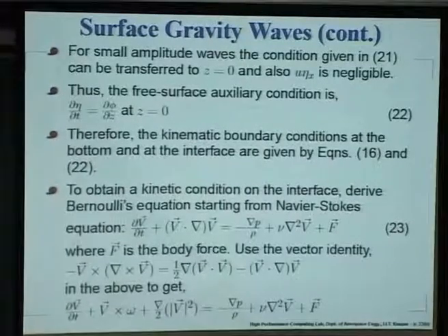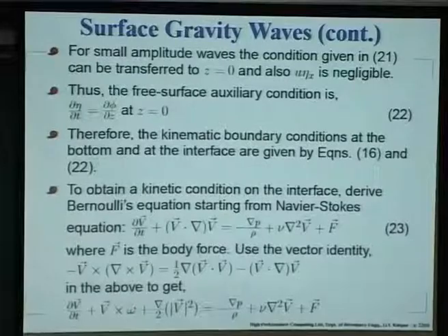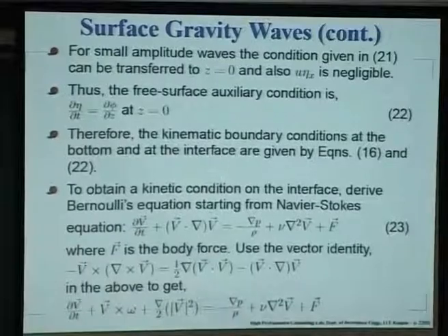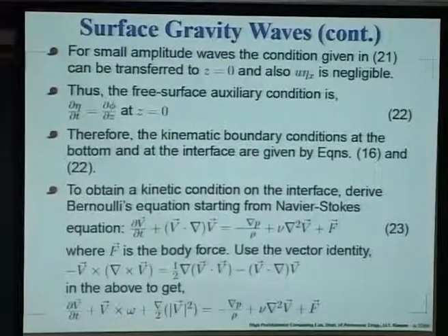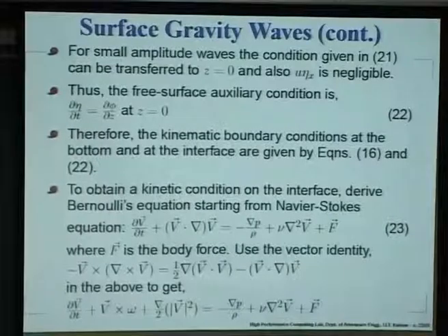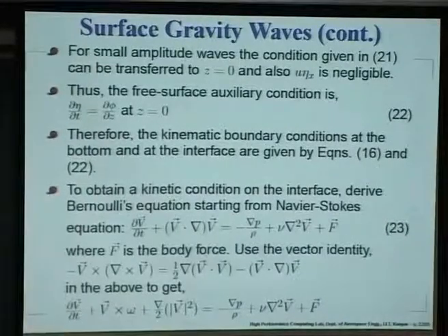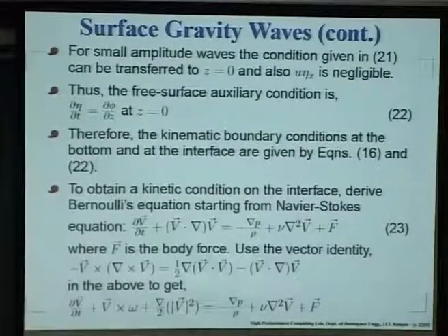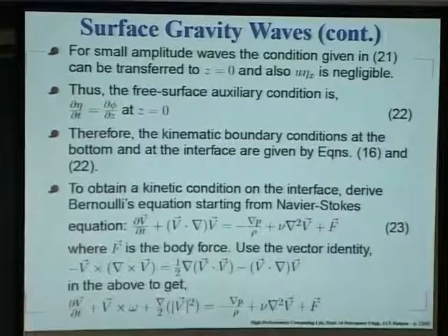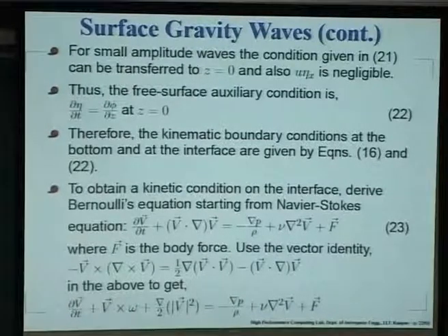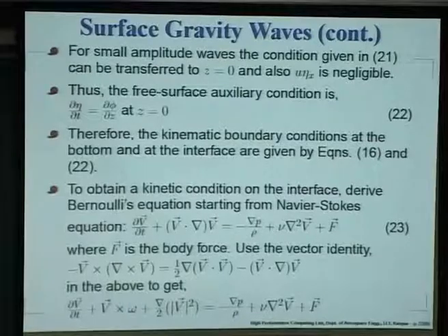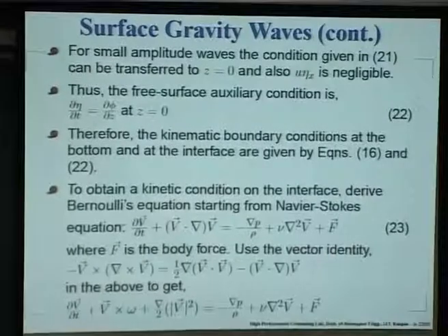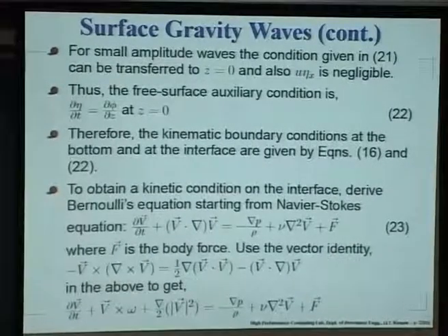So, this is another way of writing out the Navier-Stokes equation that we keep solving all the time in fluid mechanics, aerodynamics, etc. Now what we are going to do is simplify this equation. Simplification will come about by omitting the viscous term that is explicitly there, right. Then we will also say that the flow is irrotational. So, omega is 0, right. So, this term will also drop out, and v, as we have written, is a gradient of phi.